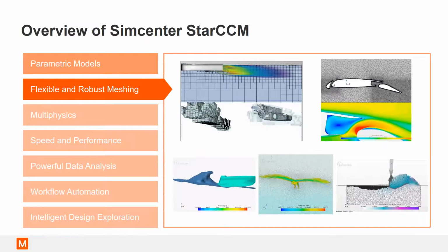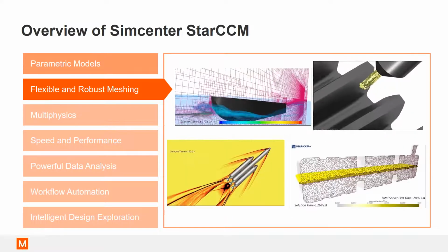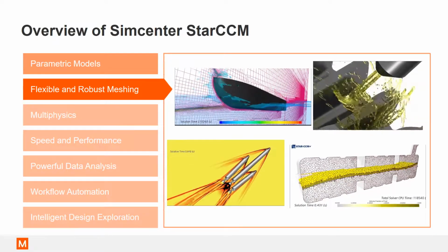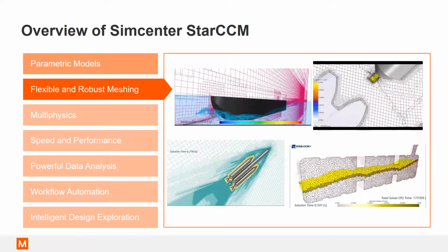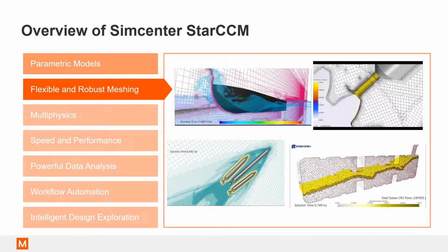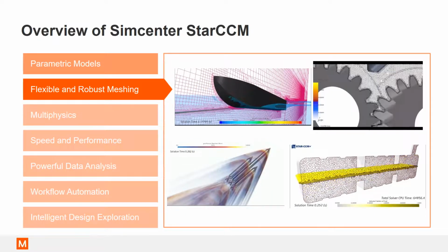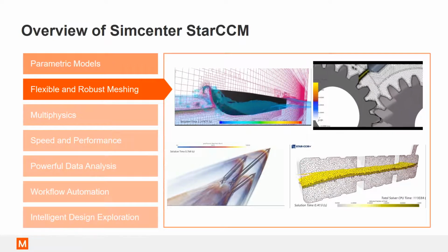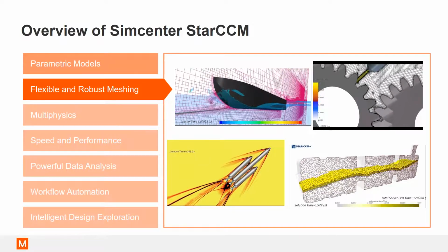But as mentioned earlier, through the history of Star CCM Plus, just recently they introduced the industry's first model-driven adaptive mesh refinement for free surfaces and overset mesh. So the adaptive mesh refinement refines the computational mesh dynamically in only areas where it's needed. So it is essentially there to capture the relevant flow features while retaining coarser mesh elsewhere. The model-driven AMR refines the mesh automatically with minimal user intervention until the final accuracy levels are met.